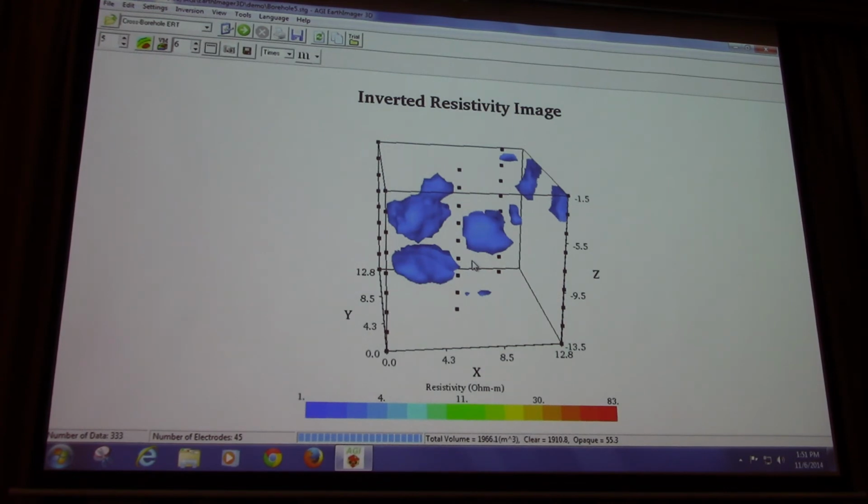And so it's a type of pollution that's very difficult to get to because it's kind of opposite of amber, right? It doesn't want to float to the top, it wants to sink. It's denser. DNAPL stands for dense non-aqueous phase liquid. And what that means is that it's denser than water. But it's not that dense. But it's dense enough that if you have a hole in an impermeable membrane in an aquifer, it will go down and it can travel with the groundwater and then go up again. And it does these crazy things. And of course, if you drill a hole, you don't want to puncture an impermeable membrane because you might actually now pollute the groundwaters underneath it.